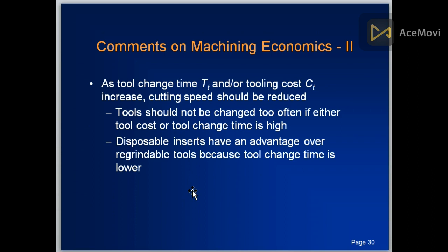As tool change time TT and/or tooling cost CT increases, cutting speed should be reduced. Tools should not be changed too often if either tool cost or tool change time is high. Disposable inserts have an advantage over regrindable tools because tool change time is lower.